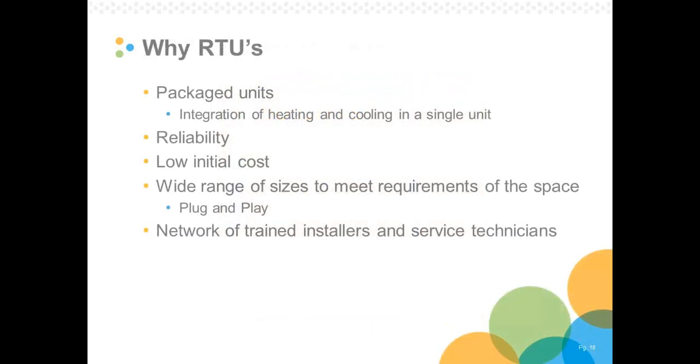So why do we use RTUs? Well, RTUs are basically a one-size-fits-all application. They are package units. They are integrated with heating and cooling in a single unit. You can very easily put these on the roof and add ductwork in order to accommodate additional space heating or cooling requirements. They are very reliable. Again, you just pipe gas to them. In the case of the Minnesota market, we typically see a lot more gas heating than heat pump.